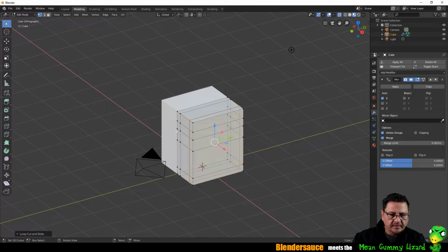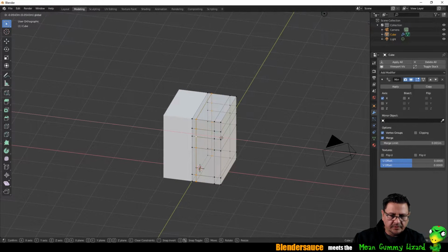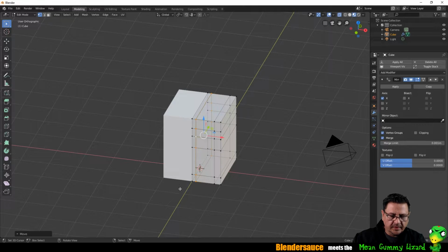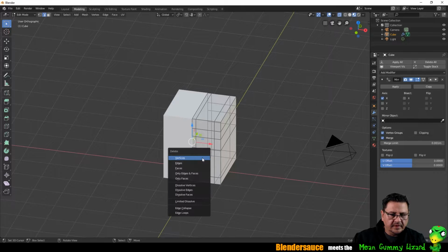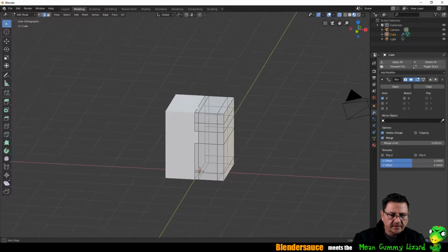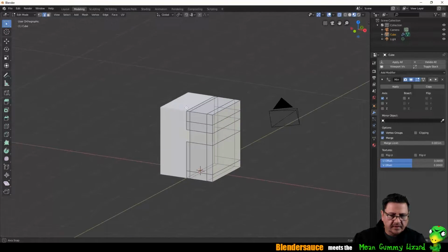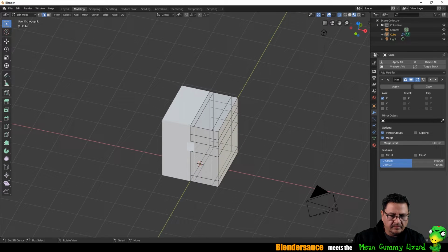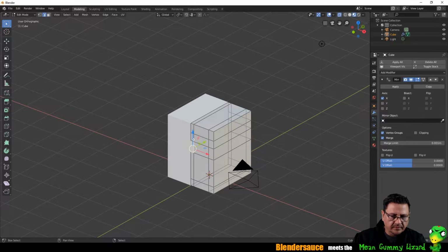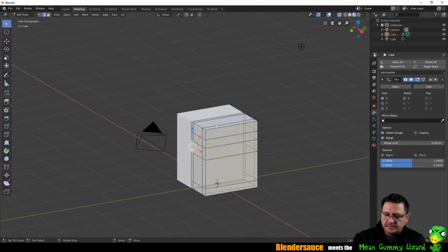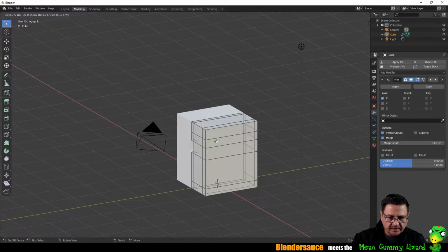So we have here the nose. I want to move that a little bit more to here, because when I go to the selection of this and delete that, the edge, you see, is big enough to stylize the nose. So we're going inwards, scale, grab this in the Y direction, like that.